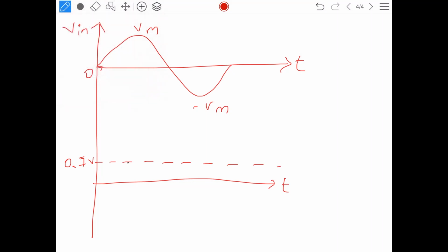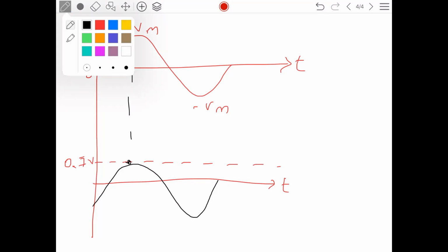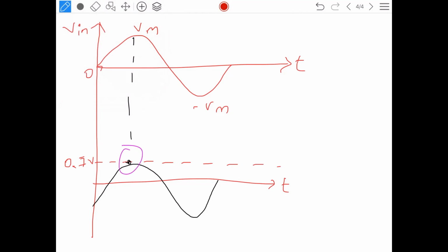Now, let us fix my positive peak here. So, the rest of the waveform just shifts below. The waveform looks something like this. If you refer to these two signals, you can see the waveform is pushed below. Now, how do I calculate these values, correct? Here blindly we wrote 0.7, I will just fix, and the rest of these terminals I will just push down. Mathematically also I have to calculate these points so that my waveform will be more accurate.